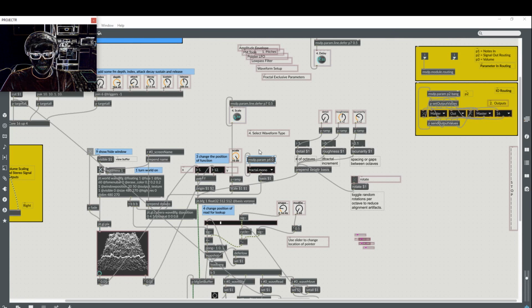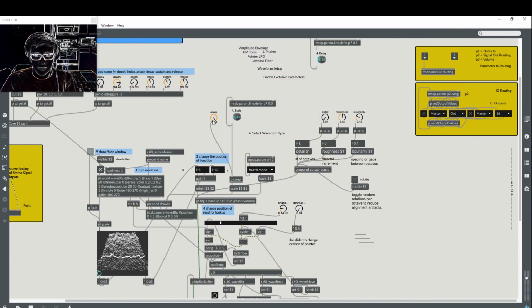That's done. The next thing that we wanted to do was to replace the scale object, the scale knob, with an MSDP dial. And you can see they've already done it. And if you notice when Timo built this, he gave it a sort of exponential curve. So it starts at a value of 0.1 as the lowest point in the scale. And it climbs up. It doesn't really reach 1 until we're about a third of the way up. And then from there it starts to climb the rest of the way between 1 and 10. So we can replicate that with MSDP dials. It's not 100% the same, but it's pretty darn close.